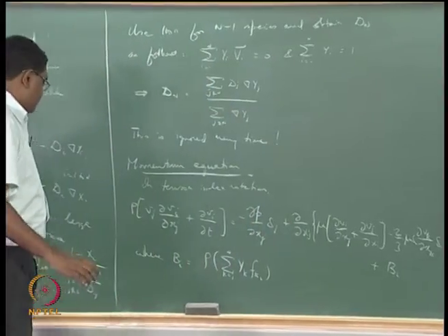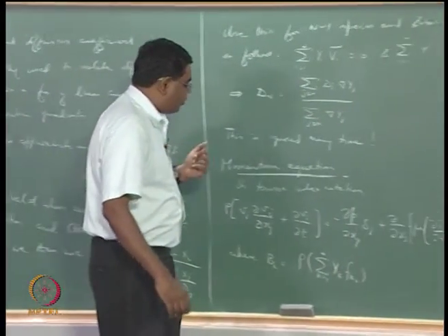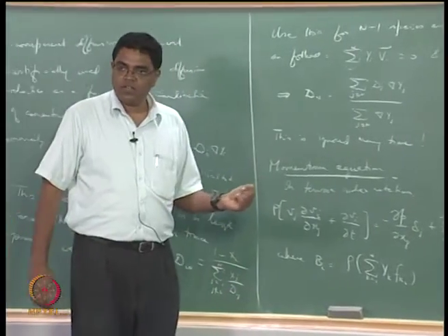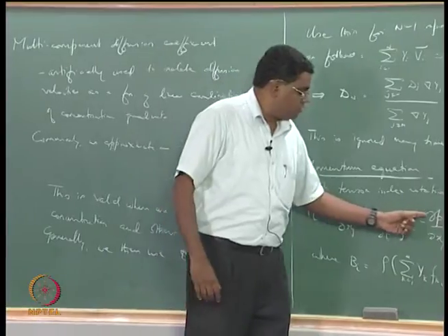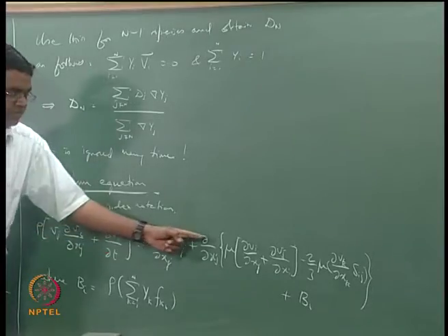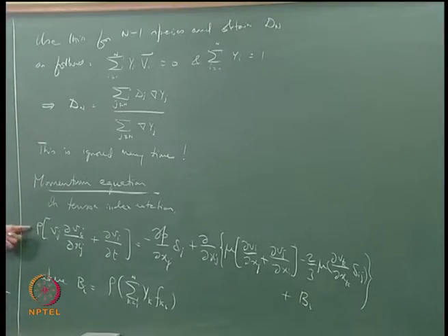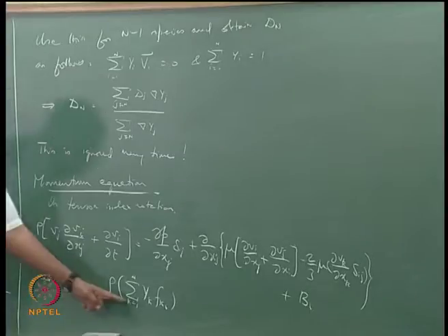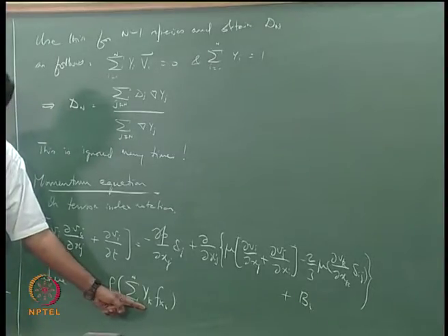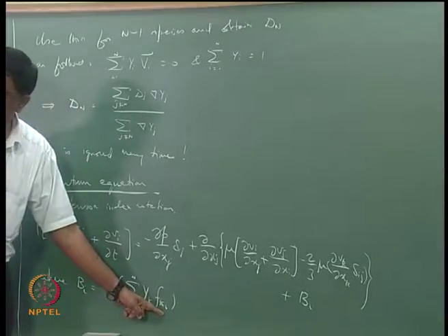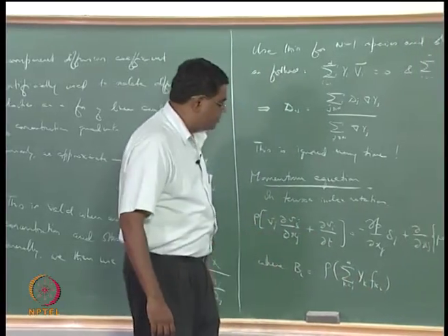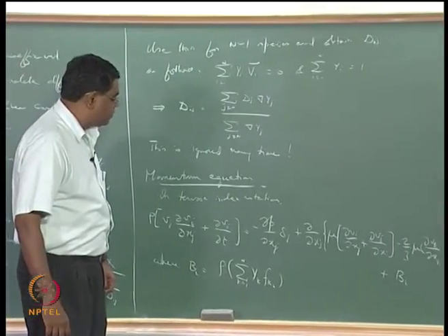So in all these things we now have to reckon with two new things that we have not seen before. The first one is pressure, and the second one is mu. Everything else is supposed to be counted as either an unknown or given. Unknowns that we have already counted are rho in the overall continuity equation, and Vi or Vj, whatever it is, in the overall continuity equation again. Yk is an unknown counted in the species conservation equation. Fki is supposed to be given to us, on how individual species are being acted upon by body forces per unit mass.